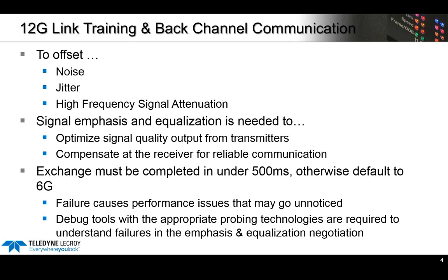The main difference with the 12G drive from the previous generations, the Gen 4 to say 12G capable drives, is we now have back channel link training to ensure that we have a noise and jitter-free link at the 12G speed.